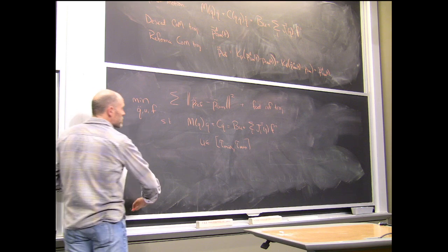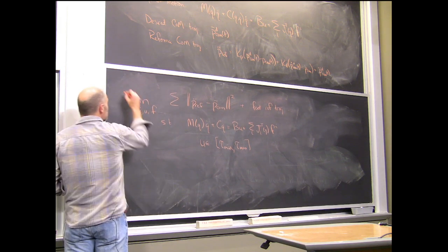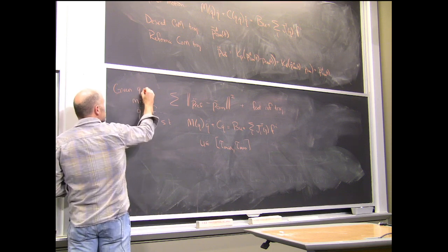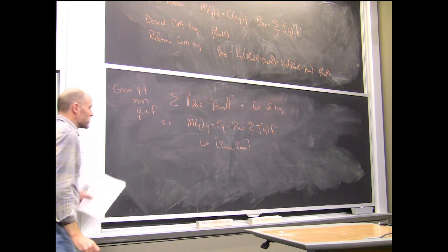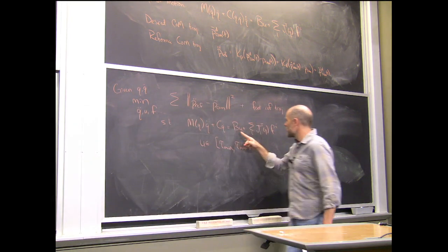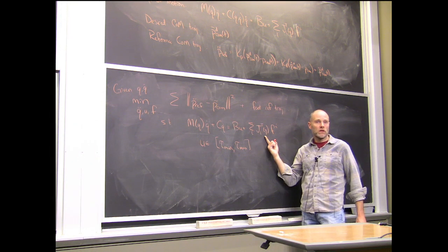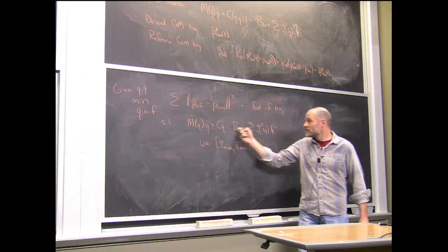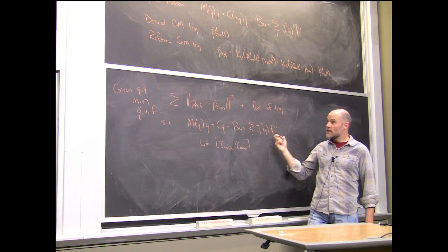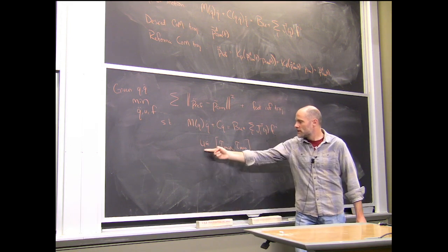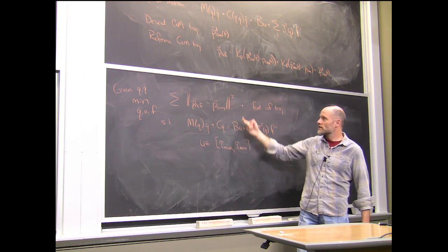What's interesting is that in the online control case, Q and Q dot are given. So all of the nonlinear terms in my equations of motion are actually constants, and this is a linear set of equations in my decision variables. These are linear constraints, and that's a quadratic objective.